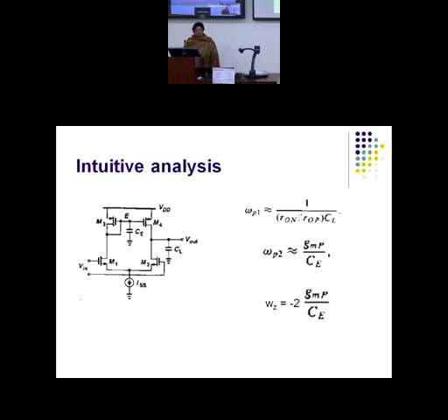M4 is a PMOS and M2 is an NMOS. So what is the net resistance at the output node? It would be, I am writing, RON parallel ROP. Why? That means I am assuming this P node comes to AC ground. Is it valid? Can I take P node variations to be negligible?